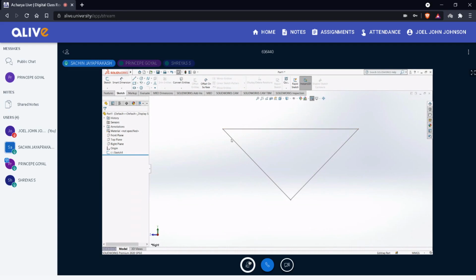See, you are outside the sketch now. You should go inside the sketch. For that, on the left side below, you can select the sketch one, right? Yeah, this one. See, got it. So now you are in the sketch. So go and select the sketch now on top. You should be inside the sketch to do these activities.